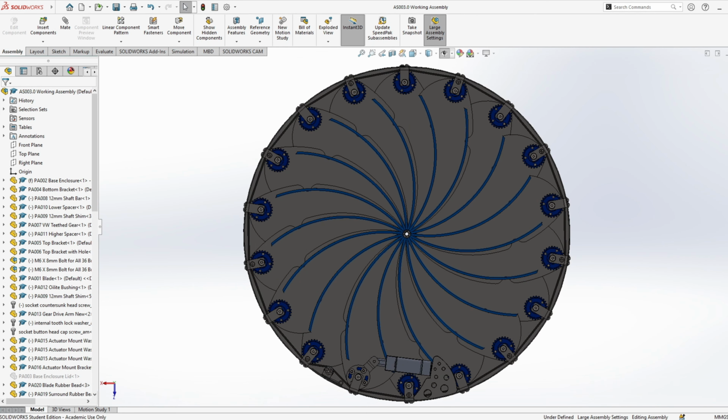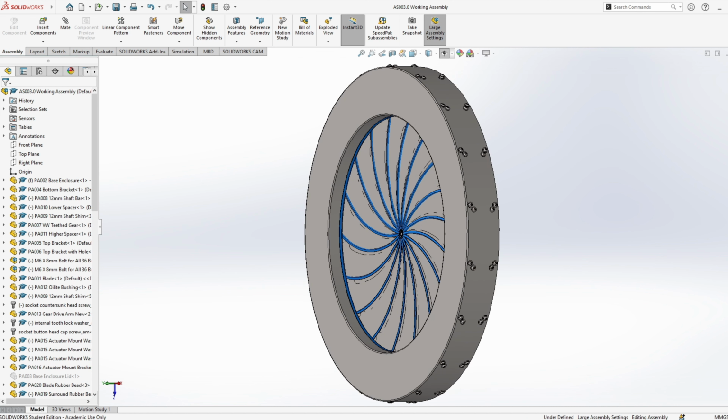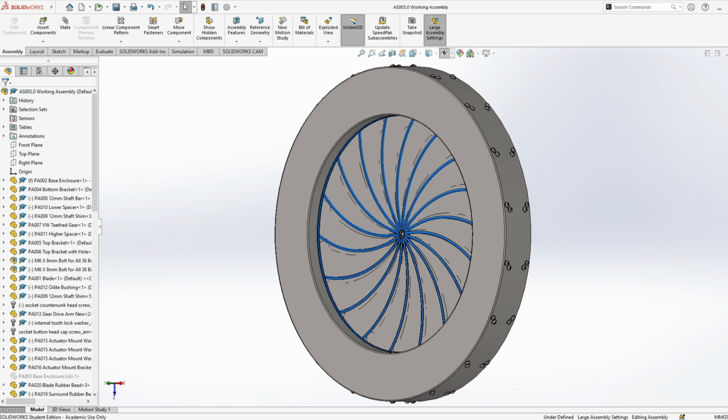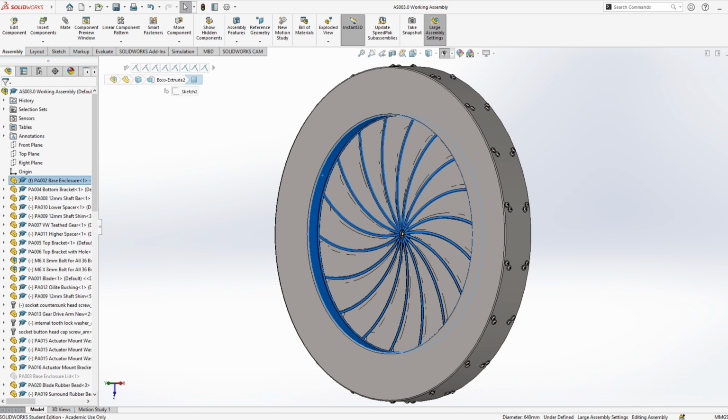Okay, so just a little example here before we focus more on the Aperture's mechanical mechanism. So if I scroll around to the enclosure we discussed earlier, we can see clearly that it's made up out of 3 pieces of sheet steel. 1, 2 and 3. So these pieces have been formed and welded together where they are only recognised as one part within the assembly. So the front face is welded to the outer sidewall, and the same front face is also welded to the inner sidewall.